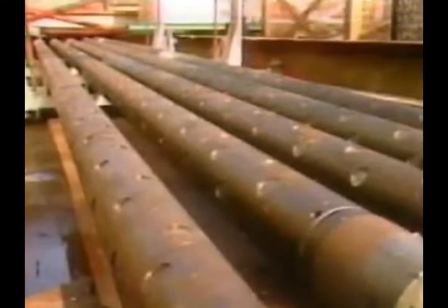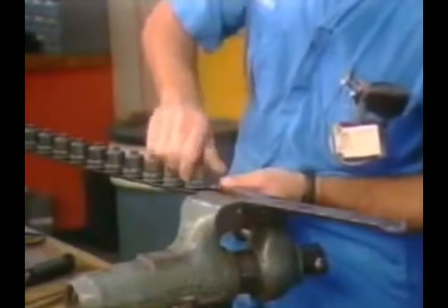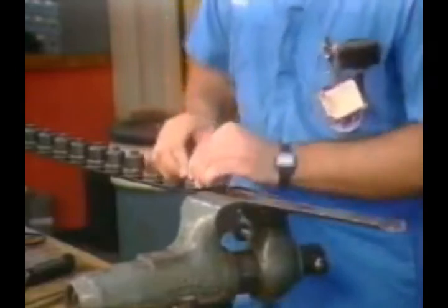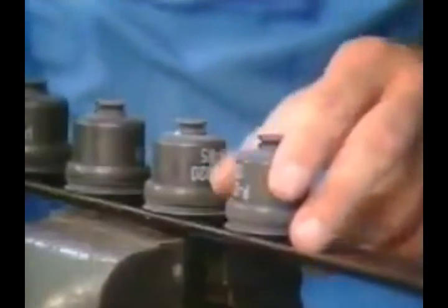Each charge is aligned with a threaded port plug in reusable guns, or behind a thinner portion of the carrier wall in scallop guns. Semi-expendable guns typically consist of a series of individually sealed charge cases designed to disintegrate after firing, leaving only the carrier strip or wires to be retrieved. In the case of fully expendable guns, only the wire line remains to be retrieved.